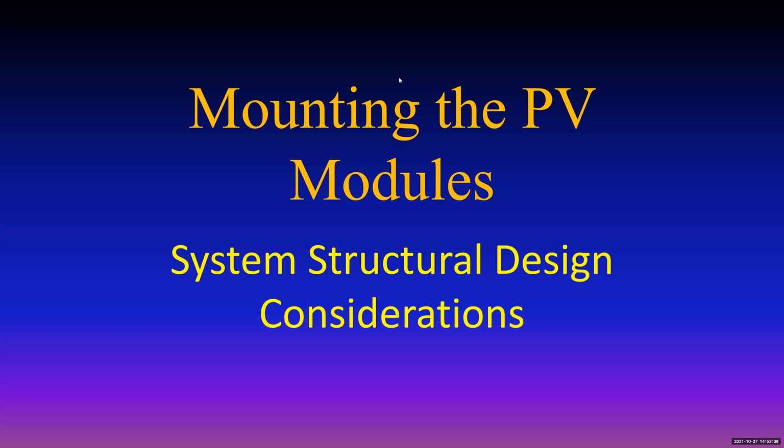How many wires are there between the junction box and the inverter? Are there splices in the junction box? The wiring from module to module is open wiring with the special insulation called type PV insulation. When you go to the junction box, the wiring generally changes over to a different insulation type, and then the wiring goes in conduit down to the inverter.